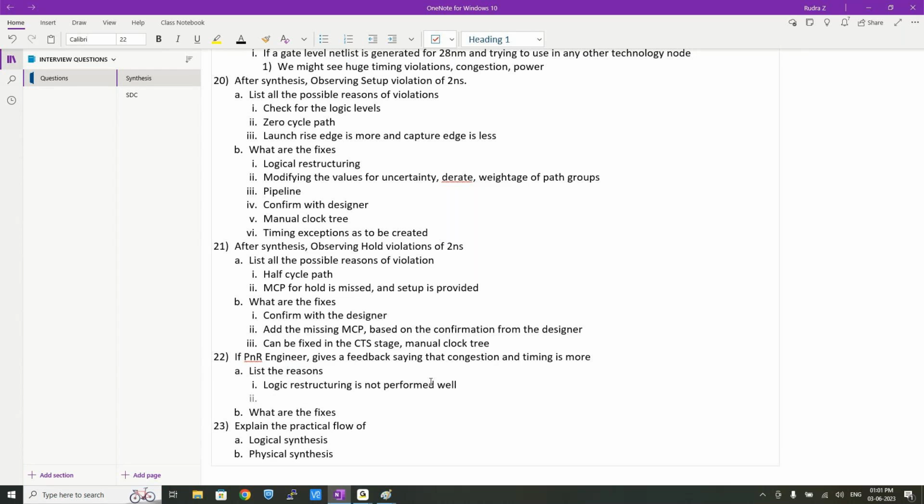That means in my design, I am seeing complex circuits, like half adders and full adders are more. I want that to be simplified. By complex circuits I mean full adders, half adders, encoders, decoders. More complex circuits are present in one timing path. As I'm using a zero wire load model in synthesis, for analysis I prefer using the zero wire load model. I'll try to analyze on that only, and on checking that I'm seeing fewer violations.